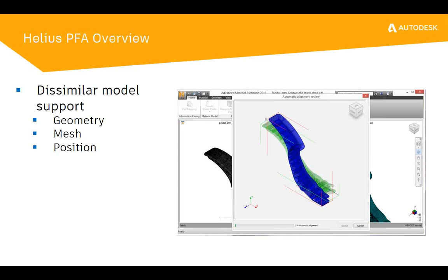Now this differs from the scripting method, which required the mesh to be the same in Moldflow and the finite element analysis package. This gives us the flexibility to design the Moldflow mesh to be tailored for the CFD or Moldflow analysis, and then have a structural mesh intended for structural analysis.